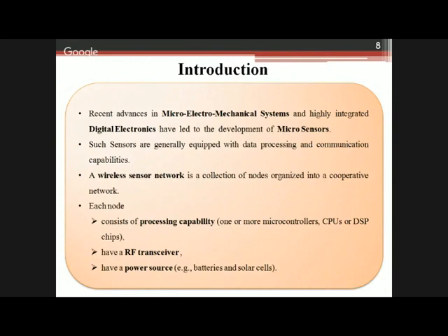So each node consists of processing capabilities: one or more microcontrollers. That's where the embedded part is coming into the picture. CPUs or DSP chips. Radio frequency transceivers, meaning transceivers which are doing both things, transmitting the data and also receiving the data. And we also have a power source, and this is the most important part, because I'm talking about sensors which have a small size, so I'm not going to give a very large power to them. We cannot connect large batteries to them, otherwise it is going to increase the cost.